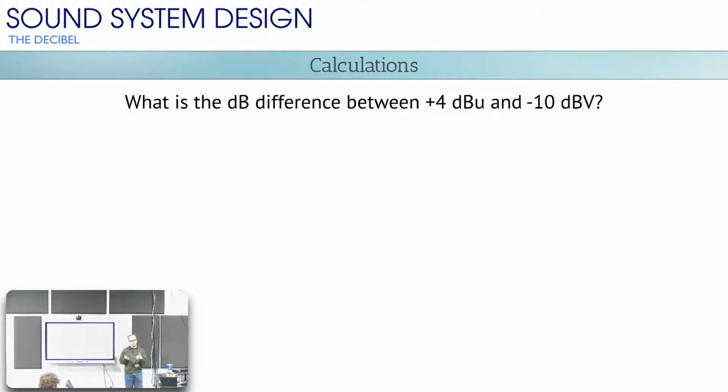It also has to do with what we were talking about earlier. It was just that comparison of milliwatts to dBu when you start standardizing that input impedance. They were trying to hit that 1 milliwatt value because that's what we were dealing with before when we standardized dBu. So they ended up with a higher voltage because they were trying to make it be a comparison to dBm. Okay? So what is the dB difference between consumer level stuff and professional level stuff?